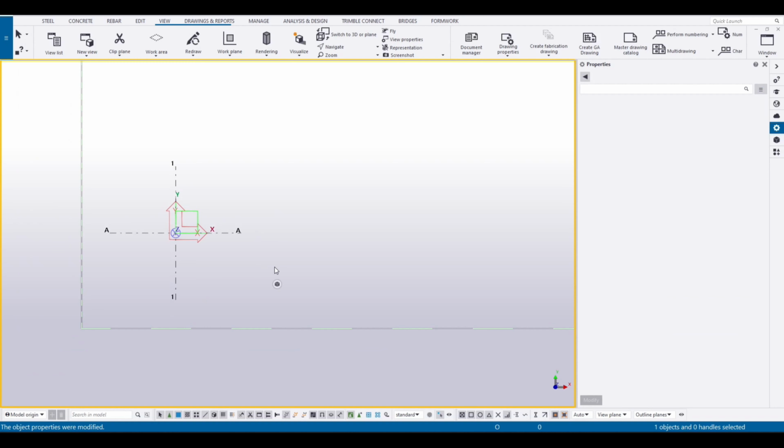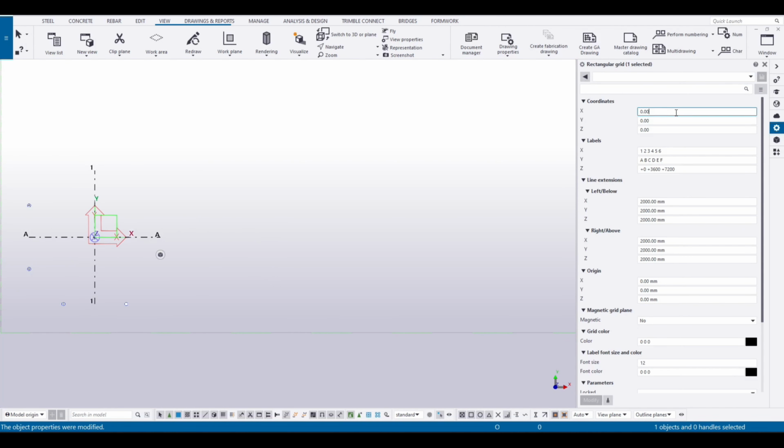Now, let's start by adding grid lines to our project. So it's going to be straightforward. You just go back here to coordinate X. The first one is the first grid line. The second one, to create the second one, you need to hit on space. I'm going to hit space bar, and I'm going to add the distance from which the grid line is going to be according to the first one. So basically 3,000 in millimeters, 3,000, enter.